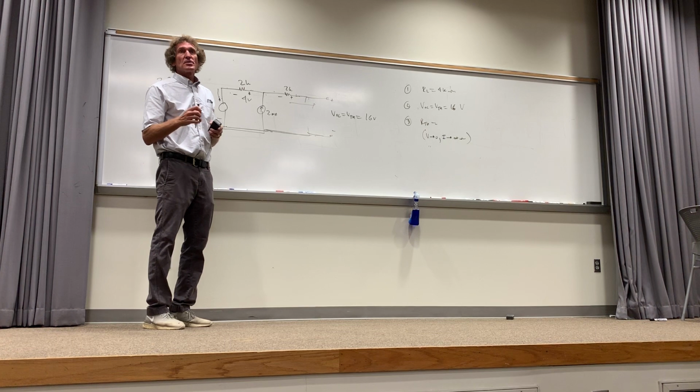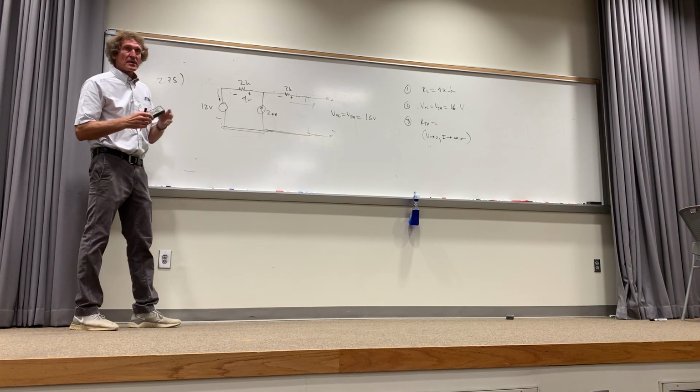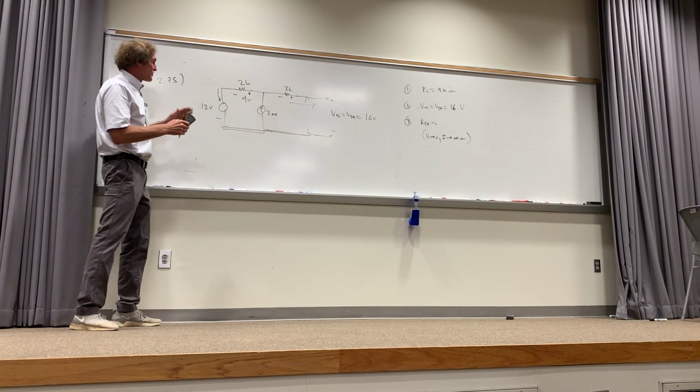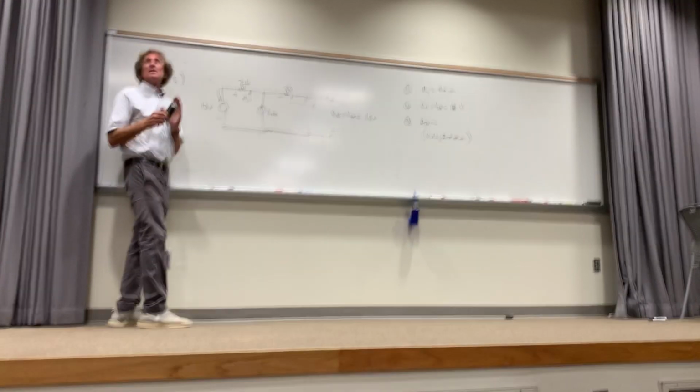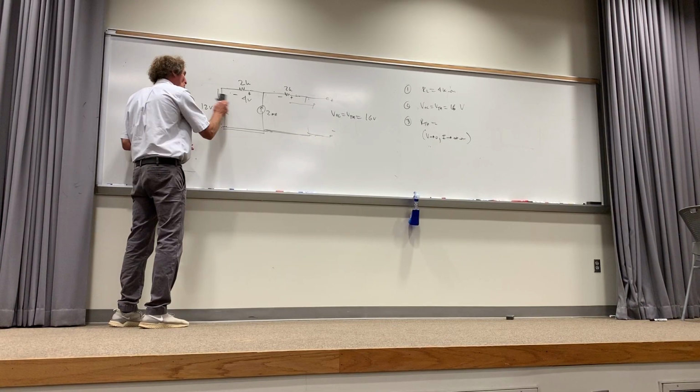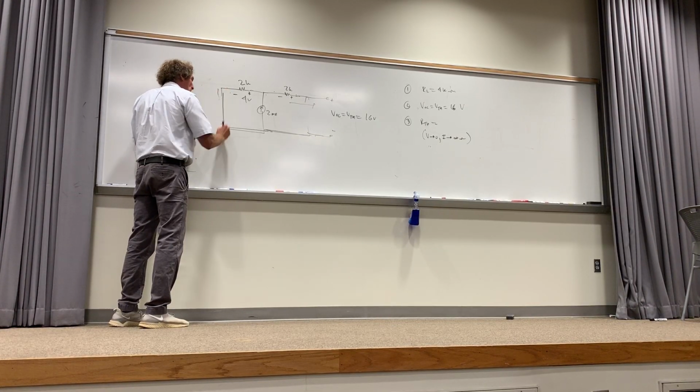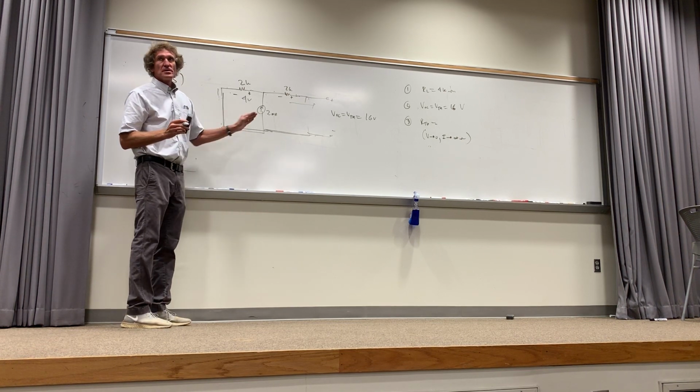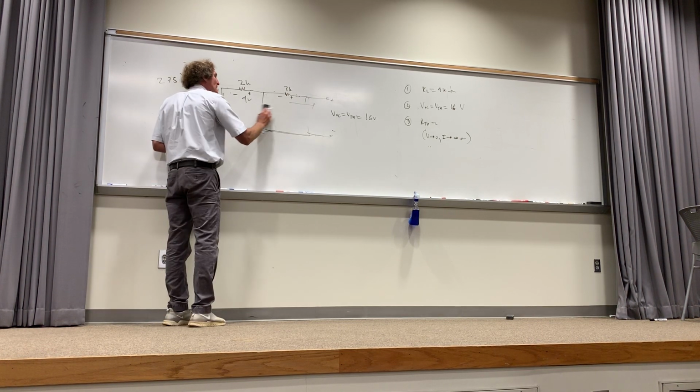All right, now we want to go ahead and do the part where we calculate R Thevenin. What did I say we do with voltage sources, class? Short circuits are wires, yeah. Wires are good. What do we do with the current sources? Just erase them. They're a nuisance.